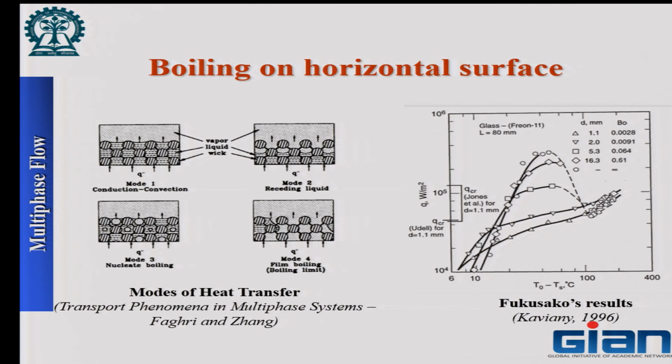But later on, quite a few other researchers tried other sorts of microporous surfaces, and were able to show that the critical heat flux can also go up. Now, what is the reason here? One of the features of using glass beads, let us consider for the sake of simplicity that these are spherical beads: if you want to increase the bond number, you need to have larger beads, right, lesser number of nucleation sites.